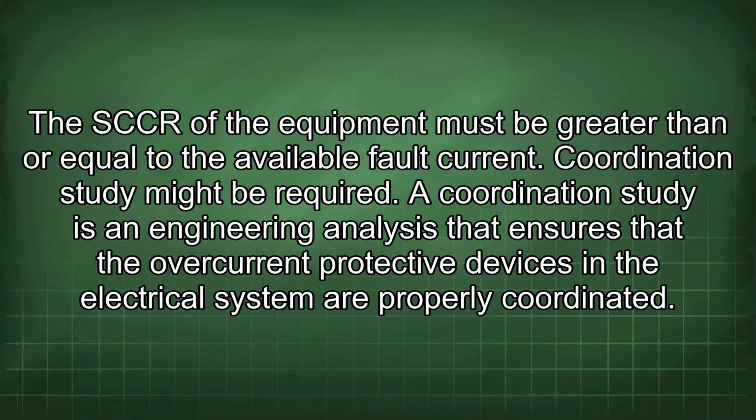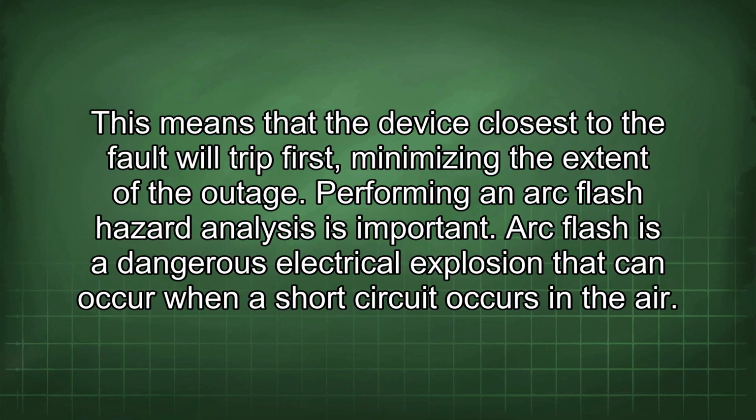A coordination study might be required. A coordination study is an engineering analysis that ensures that the overcurrent protective devices in the electrical system are properly coordinated. This means that the device closest to the fault will trip first, minimizing the extent of the outage.